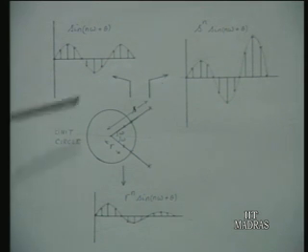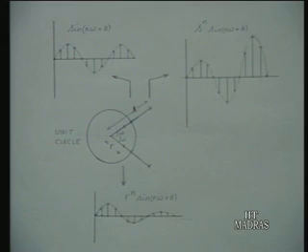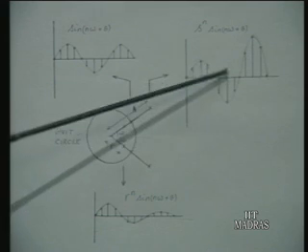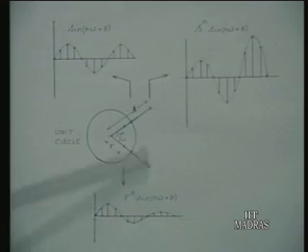If the complex conjugate poles are at a distance s from the origin, where s is larger than 1, it again indicates oscillatory behavior, but the amplitude of the oscillations goes on increasing. This clearly is an unstable behavior, and that arises because the poles are at a distance larger than 1 from the origin. Let us take the third chart.